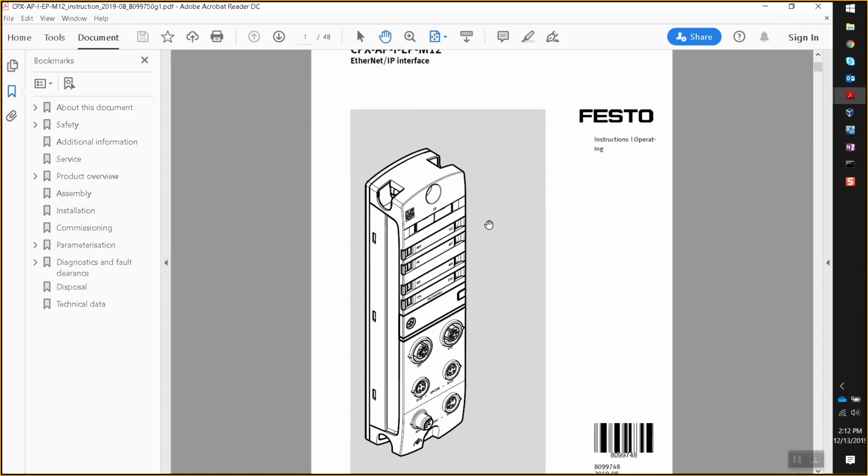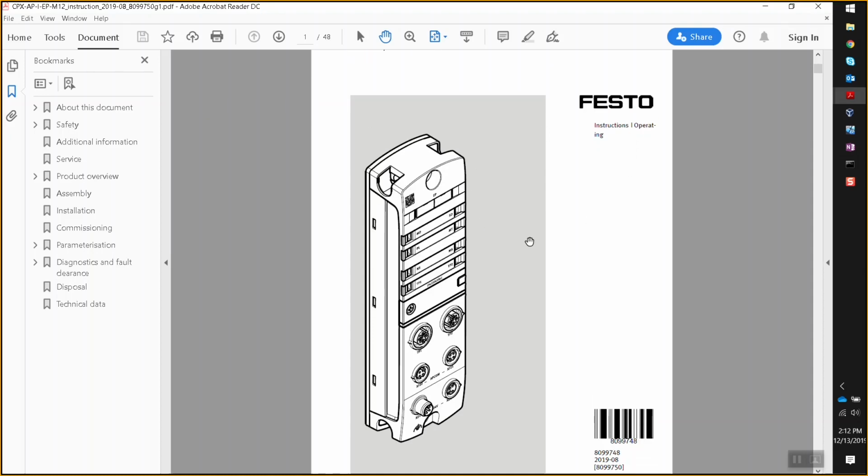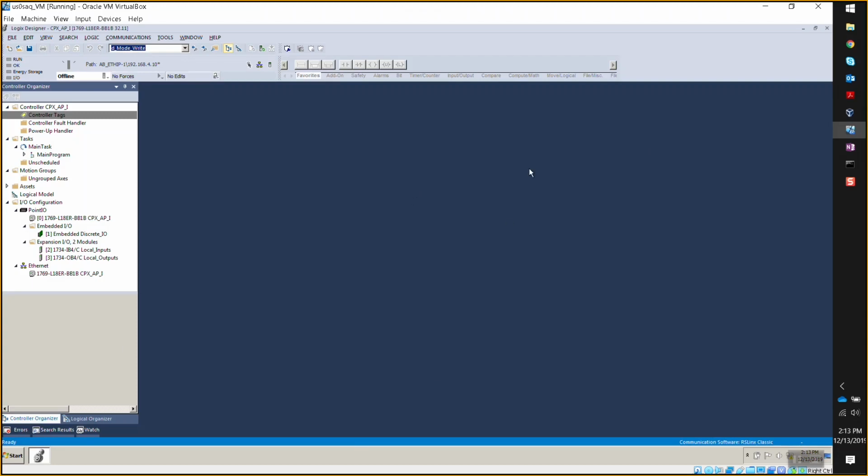I was reading through the manual and I noticed that out of the box it starts as DHCP, right? Well, that's correct. That's an ODVA requirement, and all of our devices are DHCP out of the box. It should be pretty easy to set the IP address, though. You could use Rockwell BootP for starters. Okay. And I would start with that. Okay, yeah, we can do that.